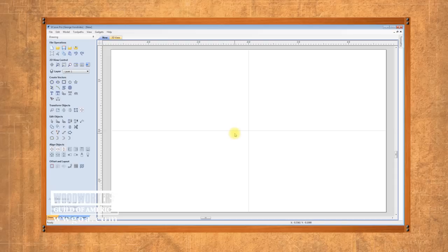Now don't create an oval, just paste an oval. So isn't that cool? We pulled that from the old file into this one. This then is the outside of our box. Now when I rabbet the lid, I want to use a 1/4 inch rabbeting bit. So that means this is the outside. I want to create an inside that's a 1/4 inch away. Let's let the computer do what it does.